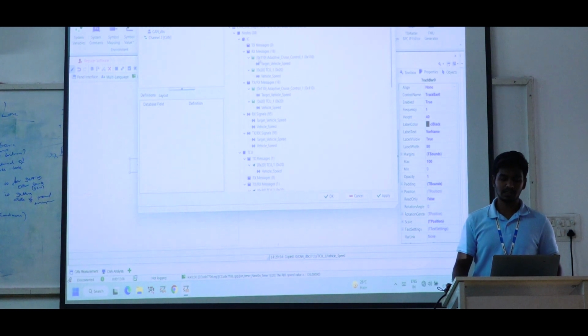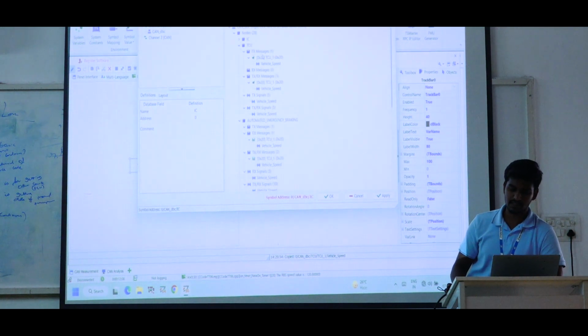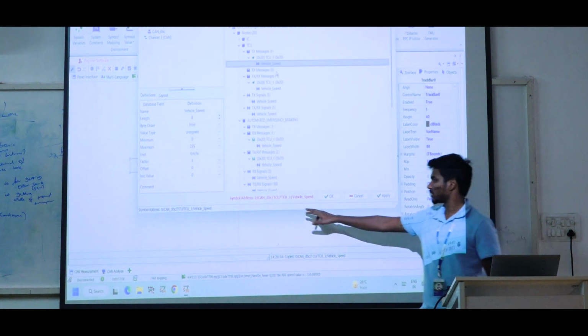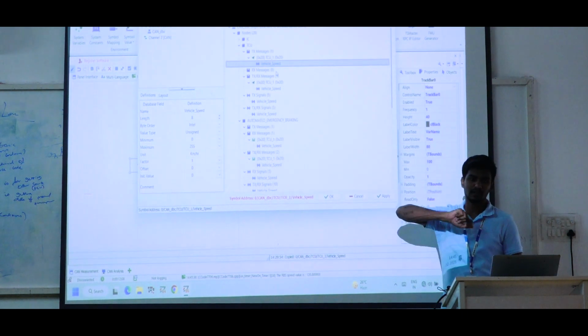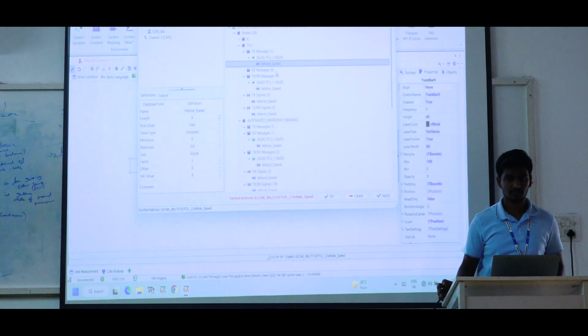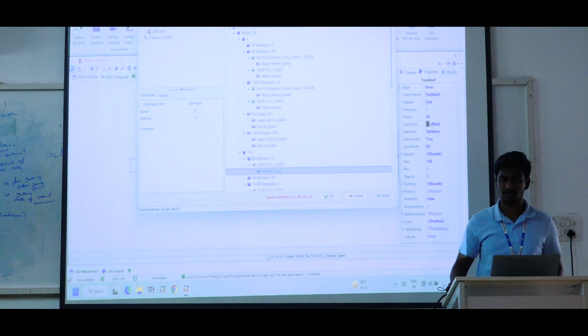Please ensure that it is a transmitting message or not. You are checking with IC. So please drop down IC and open the TCU vehicle speed. Here it will show the address, like CAN DBC TCU, from TCU message vehicle speed. Type the vehicle speed in the filters. It is showing you both IC and then afterwards TCU.